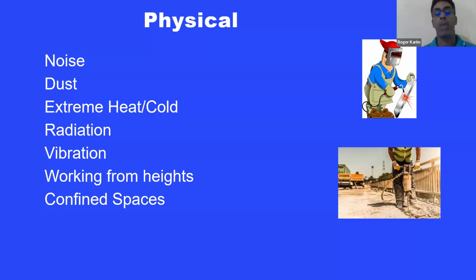So since then, what we have done, we have changed the PPE requirements for persons involved in jackhammering. So we use welder's boots. So there's a steel metatarsal plate to cover the metatarsals. So in addition to being steel tip shoes, we require now that you wear boots with a metatarsal guard.